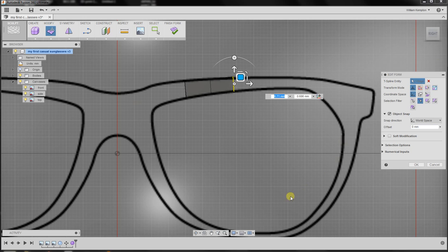So I'm going to be doing this around the whole object, and I'll link them up in the end, and then I'll make new faces for the outer edge of the sunglasses and also the bridge above the nose. And note that as the thickness of this object becomes slimmer around the edges, I'll scale it down a bit. And I'm making new faces in pretty even increments. I'll also be rotating them a bit so that the line goes in towards the center of the glass. This will make it easier later on when I model.